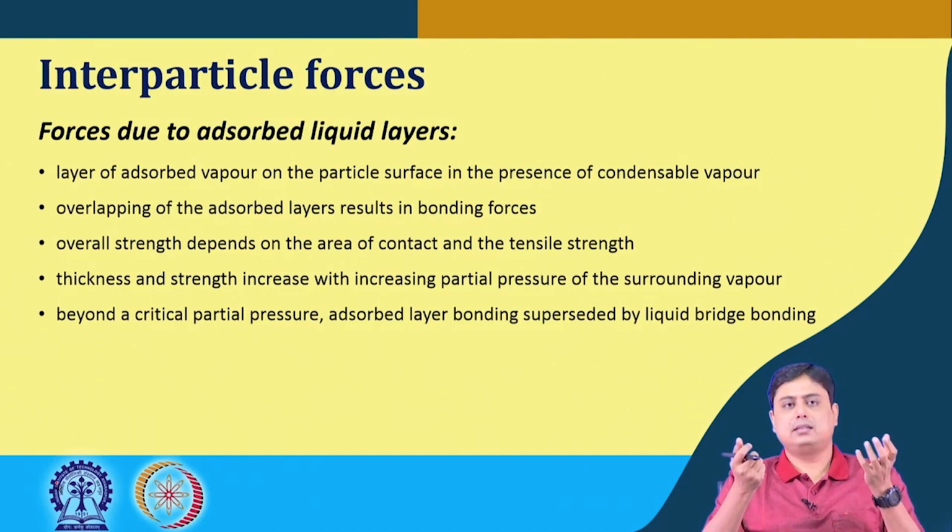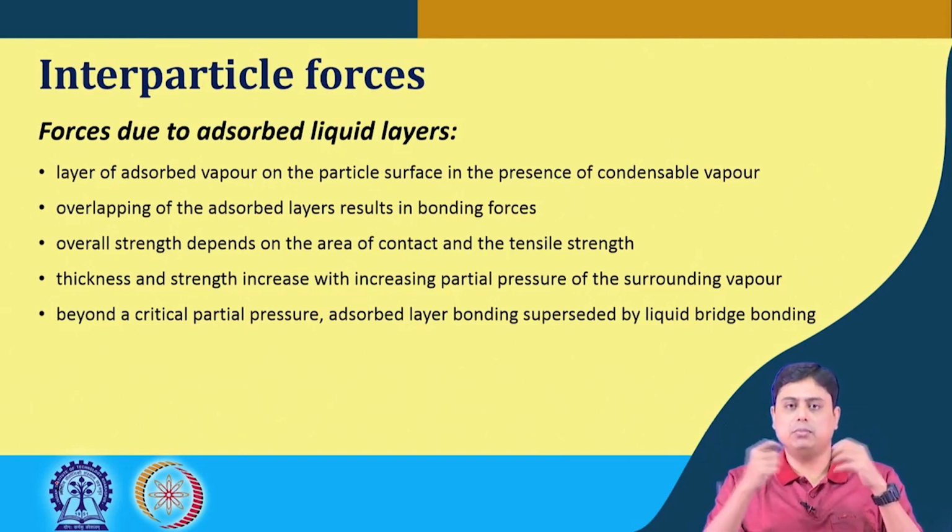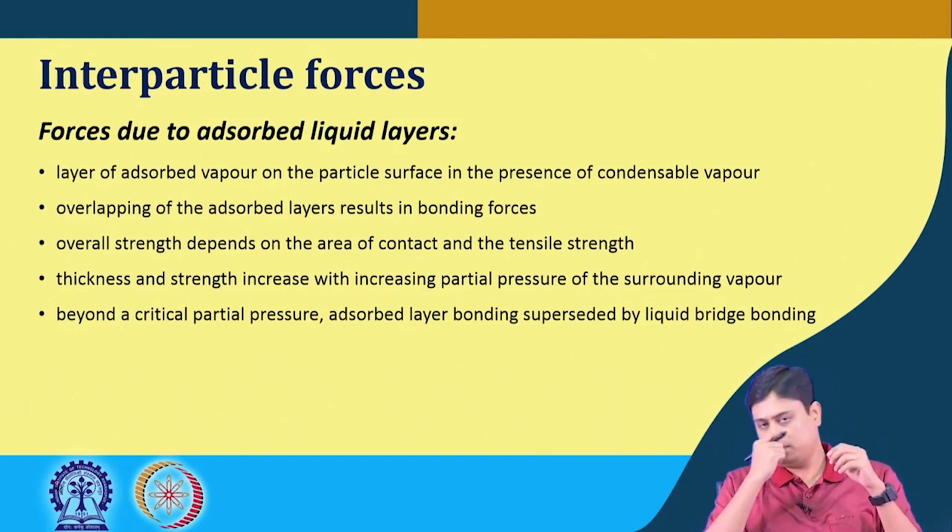Its thickness and the strength of these layers increase with increasing partial pressure of the surrounding vapor. And beyond a critical pressure, this adsorbed layer bonding is superseded by liquid bridge bonding. These layers then form the liquid bridges between the particles.